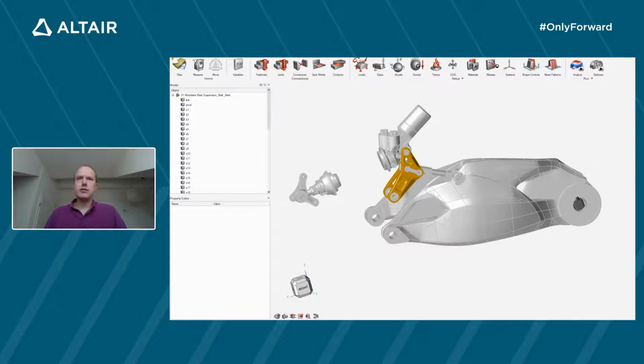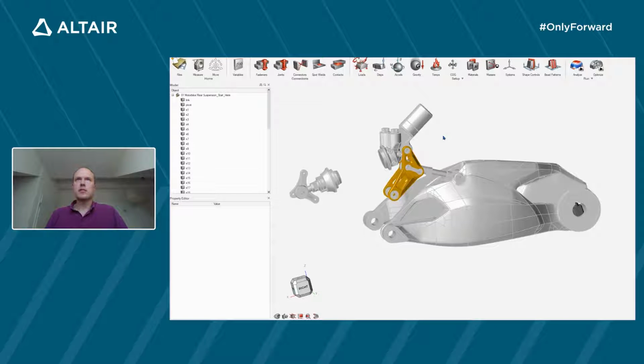Okay, so here you see the geometry assembly of the motorcycle suspension without any couplings between the different parts. So if I would start an analysis here, you would basically see the whole geometry falling apart because there are no connections between the different parts, and there is also no ground structure, no damping and spring structures connecting the different parts of the assembly together.